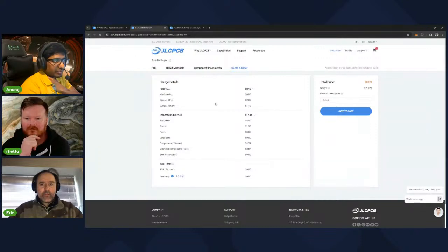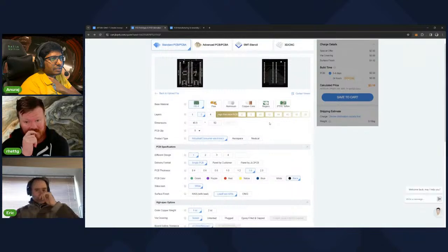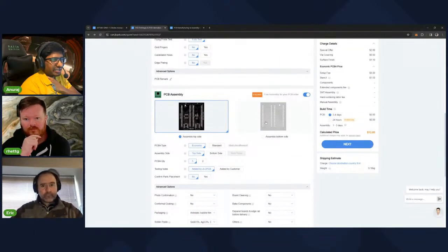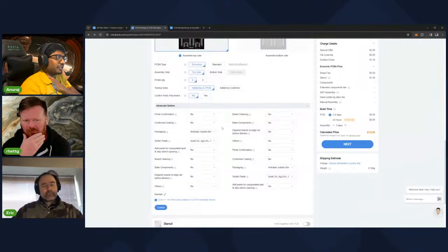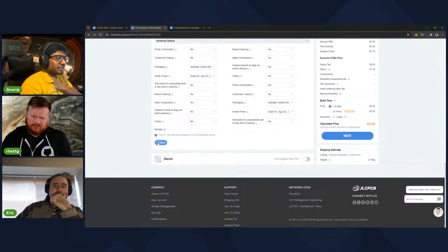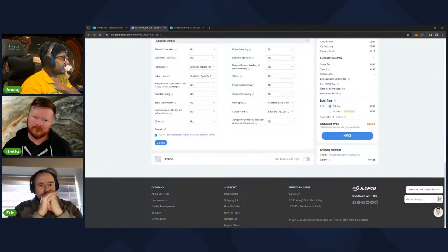It's like they're placing the parts. I don't know why it didn't. Maybe it was because of the positions. When I exported from KiCad, I didn't have the orientation set in the schematic itself, I think.